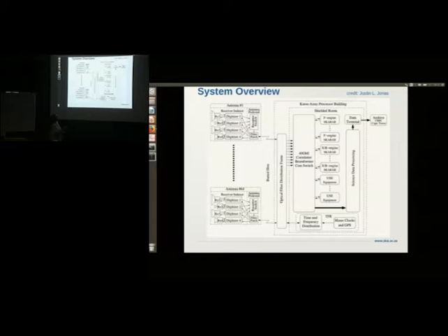The receptor switch then goes to the fiber patch, and this is where the signal gets transported to the Karoo array processing building via fiber, which is buried 1 meter under the ground for temperature stability. Once the signals get to the Karoo array processing building, all the data gets plugged into a 40 gigabit Ethernet switch.